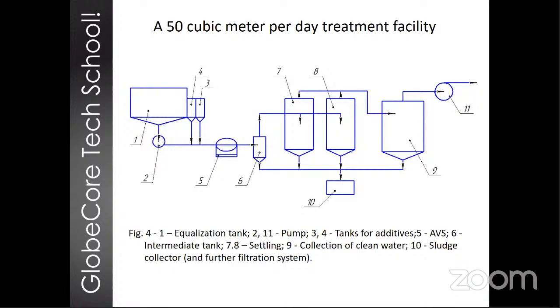The difference is that when in contact with water, the water vapor contained in the flue gases also condenses, diluting the original water. It should be noted that the amount of water vapor in flue gases is very significant. So you can have about 9.5% of CO2 and about 18.9% of water. So it can be assumed that the condensation of water vapor in this arrangement will be almost complete. So for 1 cubic meter of this flue gas, the increase in water will be maybe 0.15 cubic meters of additional water. As a result, we discharge into the atmosphere practically pure nitrogen. This means that the process is very environmentally friendly, with a very small environmental footprint.